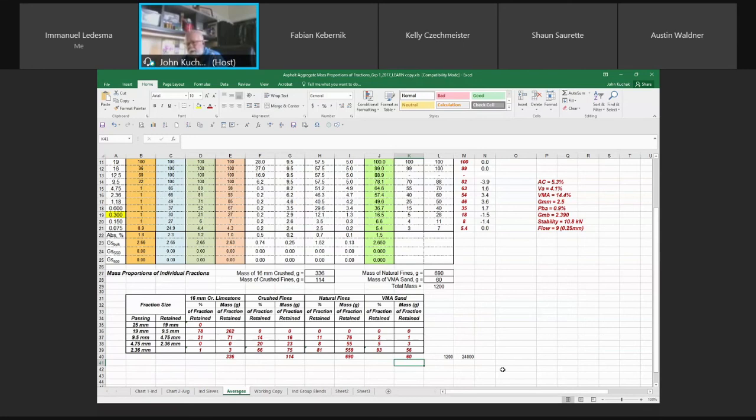You typically use water to improve compaction, and then you use water before placing the concrete. Got to read the question, guys. It said immediately before placing concrete. It has nothing to do with compaction. Compaction's already been approved. Yeah, you use water for compaction, but that could have been done a week ahead of time. So be careful when you're straight copying spreadsheets. Same thing can happen. Any questions?